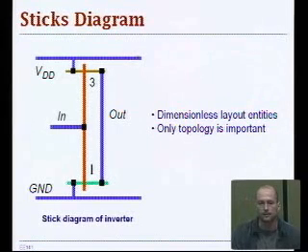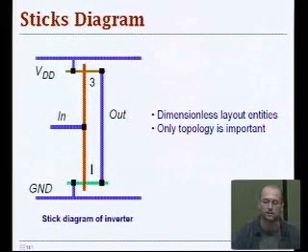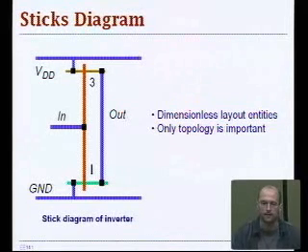But the problem with that is that oftentimes you don't get really what you want, because the tool decides to position transistors and contacts the way it understands that diagram, and sometimes you don't have the highest density layout, and you would eventually want to do some manual intervention in the layout design. But oftentimes it's a good starting point, and then you can modify your layout from there. But hand crafted design is still the most valuable.